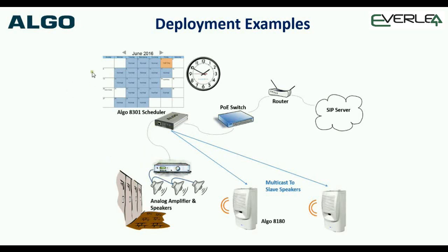At the same time, it will also start managing your SIP paging speakers, e.g. the 8180s or 8186s, etc. So you can start setting up your multicast groups and paging and all that kind of thing through to the new part of your building, which has all got fiber through the floors, etc. And finally, the other thing it does is it's got scheduler functionality. So we can have years, days of the week, and set a whole bunch of different scheduled plans into that day. For example, on a school, we could set up the bell environment.